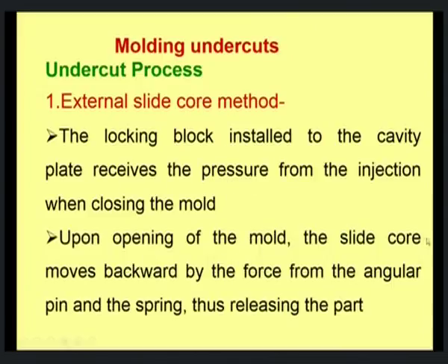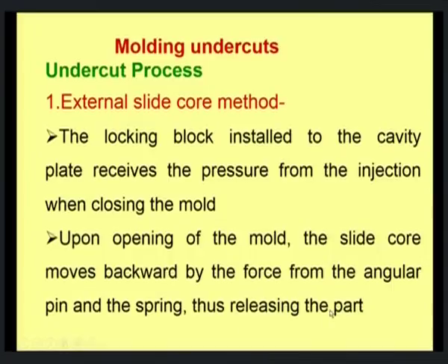Upon opening of the mold, the slide core moves backward by the force from the angular pin and the pushback spring that is provided, thereby releasing the part more easily.